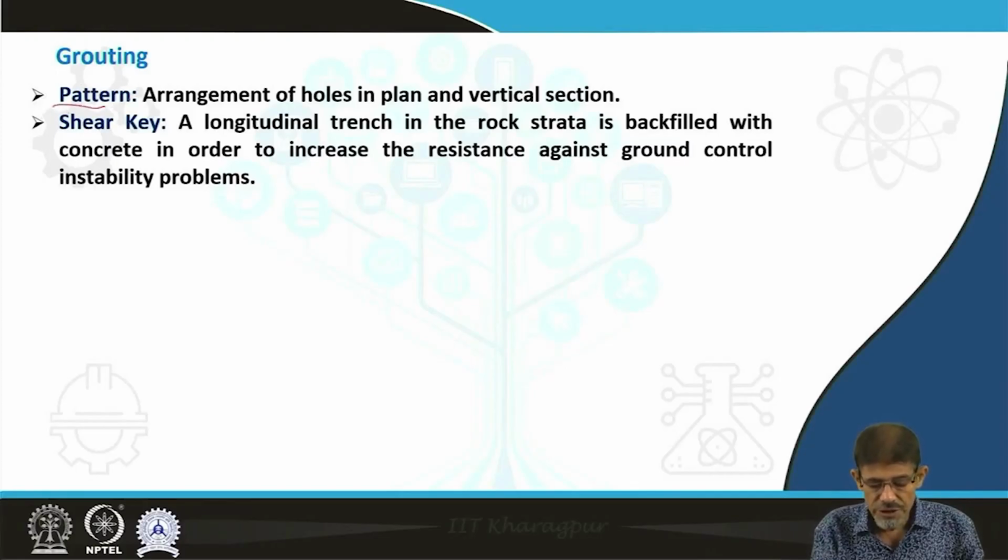For this, regarding the hole plans, because grouting is performed in drilled holes, the arrangement of holes in plan and vertical sections is predefined as per design, based on the nature of strata as well as the engineering structure which we are going to construct on such strata.